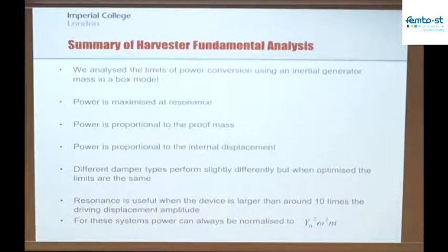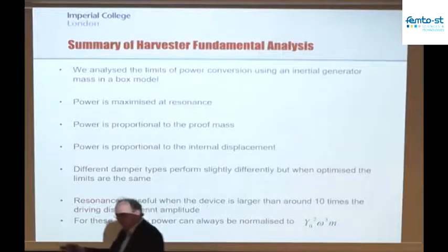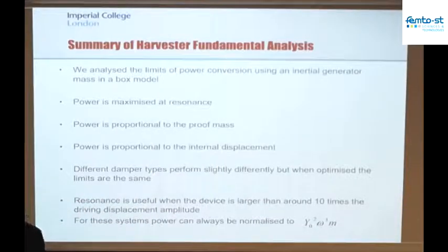If that's not the case, then there's not very much benefit to using resonance. In fact, there's only a detriment to using resonance, because if you end up operating below the resonant frequency, as we saw, the power falls off very, very dramatically. So if you've got a device where the vibration is small and the device can be big, then you definitely should use resonance. If it's not the case, then you probably shouldn't, because if you do use resonance, you're not getting much of a benefit from it.